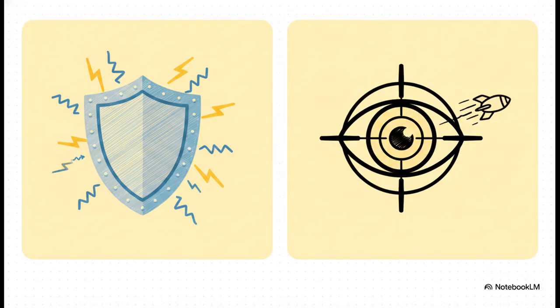Now, because of those two specific scenarios, you absolutely have to know the difference between regulatory control and servo control for the exam. Regulatory control is all about disturbance rejection. It fights to neutralize disruptions and stabilize the whole system. Servo control, on the other hand, is about target tracking. Its entire job is to rapidly and accurately follow a target that is constantly moving.